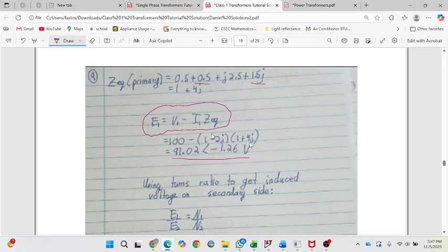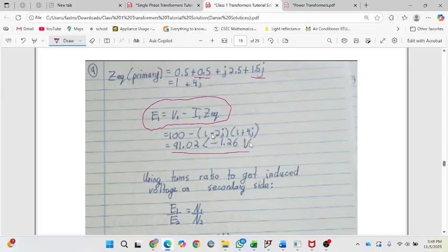Because the calculator could convert. I don't know if you all noticed in your calculator, you could click shift and mode or something, and it could actually convert it from phasor to complex. I don't know if you saw that before. So that means the calculator knows how to convert from complex to phasor and phasor to complex. So if you put in both, it will know to convert it to whatever form. So it knows how to do it. Everything doesn't have to be in one form. So just make sure when you're doing it in a calculator, you bracket it off. Yeah, I did this tutorial and on my calculator, everything was in phasor form. I just have to convert it back. It doesn't really matter, you get the same value. Okay, right? Good question though, but it doesn't matter.